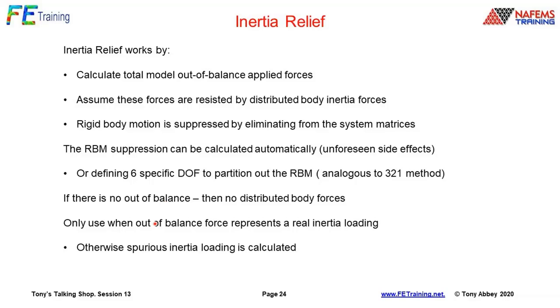If there is an out of balance force in there, it's best to use that approach when that out of balance force represents a real inertial loading. And I'll have some examples of that coming up very shortly. If you don't, then you're saying, okay, my out of balance forces, somehow they're balanced by inertial loading, and it can become a meaningless type of loading. I'll show an example of that a little bit later on. So we can't just use it to fix up a model. We want to be thinking about inertial relief.